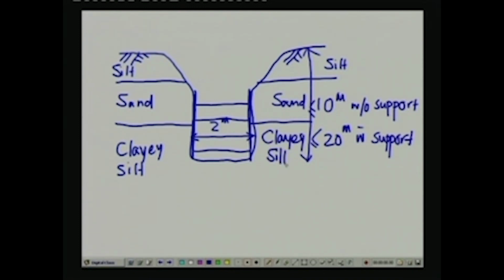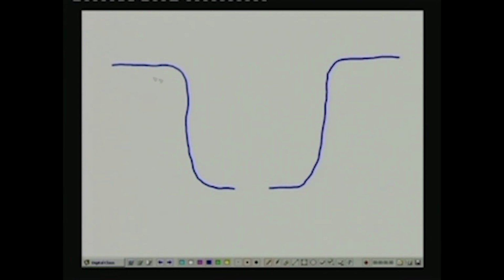Now, as the excavation progresses down, you could take disturbed samples from the excavator bucket itself, or you could try to recover some undisturbed samples. Now, how do you do that? Let us try to understand how it is done in case of a clay deposit, because that is where you might actually get a very high quality undisturbed sample during the excavation of the test pit itself.